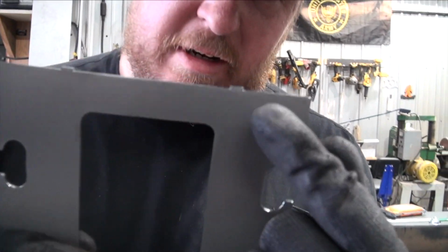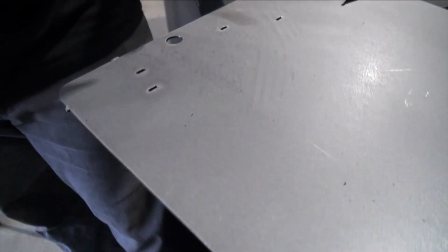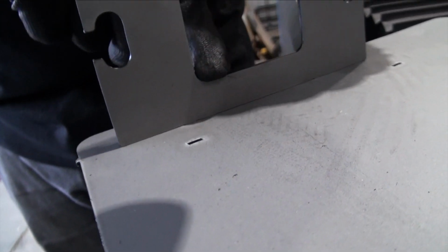So what we're showing here, that's our tab, and it's going to fit perfectly into these slots. After everything is formed up, now we have a locating feature that's going to guarantee that this part is always aligned in that slot right there. So using tab and slot design for sheet metal with your laser will greatly improve your production flows, reducing your bottom line, putting more money back into your pocket.